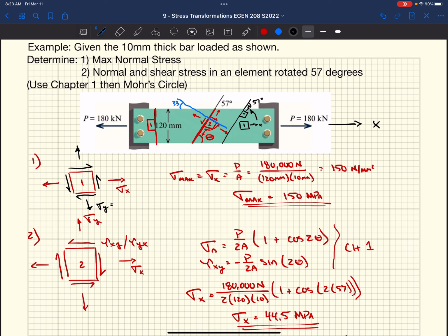We said sigma y equals 0. Tau xy equals 0, right? So we really have 4 points on this block, or 2 coordinates. We have a coordinate that we can use on the X face, and a coordinate we could use on the Y face. And that was all based on the known point, a known stress state, okay?